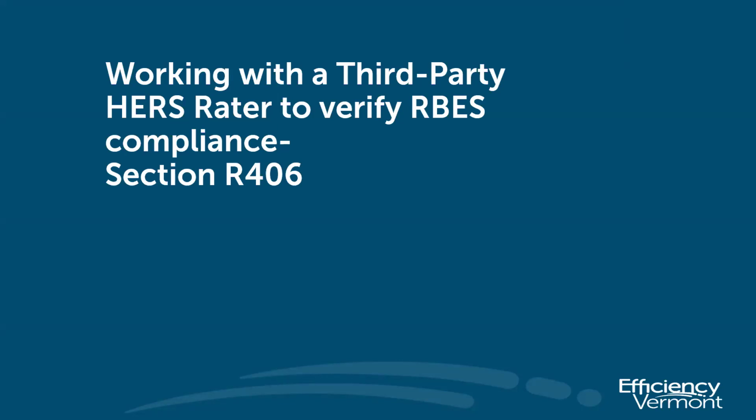Great. And thanks. Then Bruce, you have a question: what temperature does one use from the HVI table for the sensible recovery efficiency? 32 degrees would be, I guess it doesn't say specifically in RBES what to use, but I think for our climate zone, 32 would be considered the rating basis.